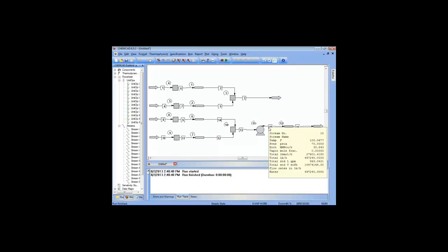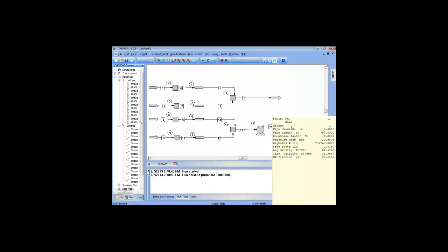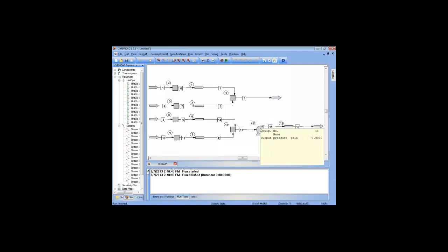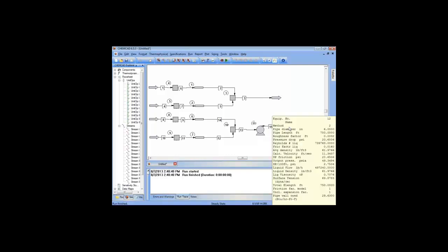If you wanted to get it real accurate, in order to have it solve automatically, say you change things here, the way we've got it set up now, you'd have to use a controller. Adjust the pressure in this pump until the pressure out of this pipe, based on the flow rate, is 50 pounds. Similar to what we saw up here, but again, we don't really want to use controllers.